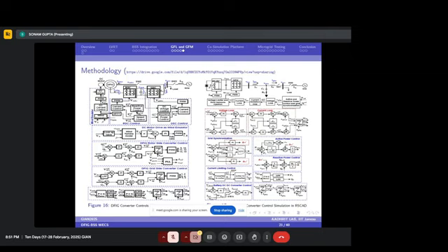So this is the methodology for the DFIG converters as well as for the battery storage system converters. Here on the left hand side, this represents the control for the wound rotor induction generator, and these control schematics, or block diagrams, are for the hardware controlling. All these controls are implemented on the hardware system. Here we can see DFIG is connected to the DC motor, and the motor is controlled by a DC drive, which is acting as a wind emulator.